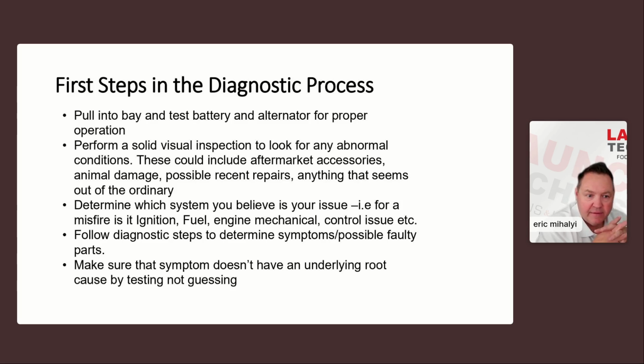Can't tell you how many times I've had that, and I've had a couple of really good techs chasing their tail, and the car needed a battery. Now they were flabbergasted. They're like, I don't understand. I drove it into the bay. You drove it into the bay. We did this. We did that. Yeah, because the car is preserving the battery for as long as it can. That's what modern cars have the ability to do until it's absolutely dead.